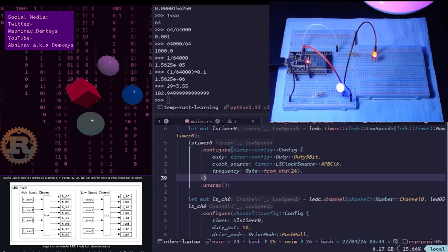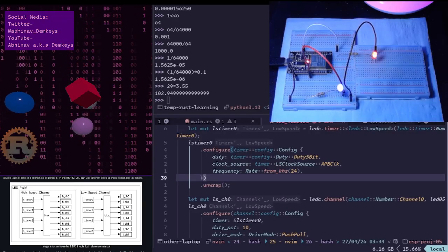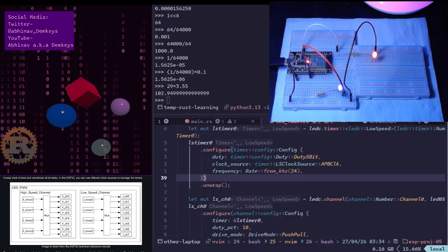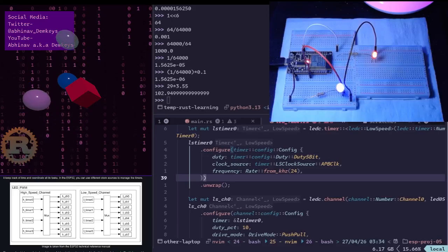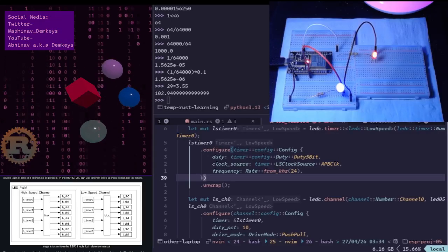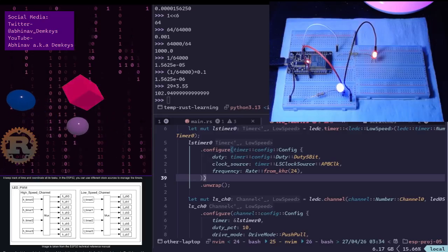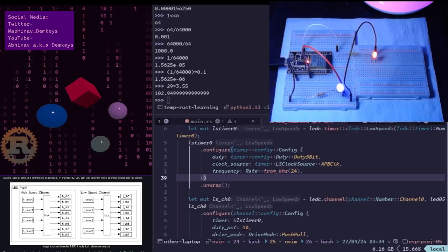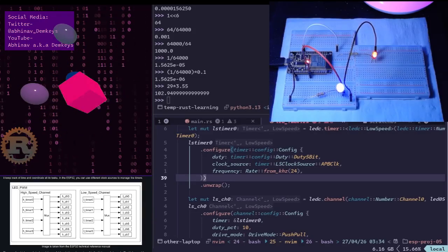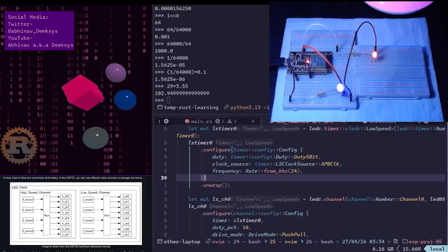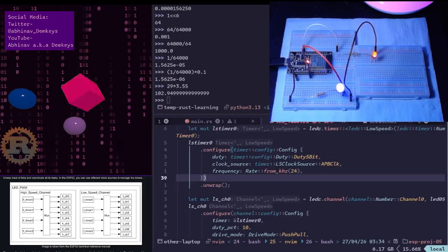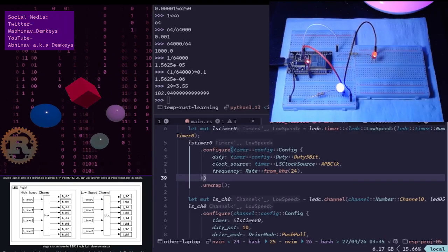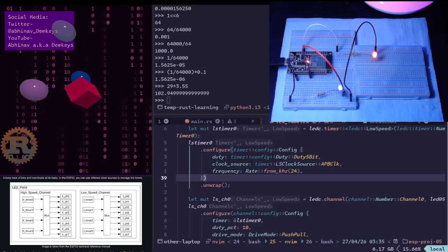Amp units, yeah, that's microamps. Okay. We can close this. Yeah, approximately 43 microamps versus 100 microamps plus on the original. So in the C3 Super Mini, it would be 43 microamps in deep sleep, whereas in the original ESP32, it would be 100 microamps.